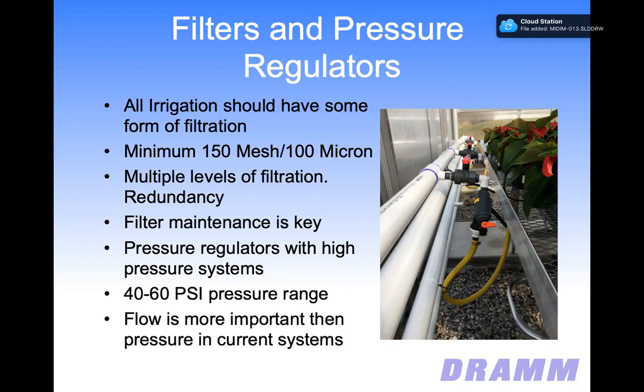be talking about. And whenever we talk about design and what we're able to accomplish with sprinklers or emitters, we want to talk about flow more than we do about pressure. Everyone seems to say they have great pressure. We are much more interested in learning more about your flow capacity when it comes to deciding how much we can water at any given time.